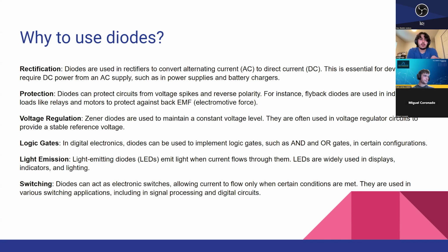Yeah, so diodes are basically like a brake, right? You want to prevent something from happening in your circuit. They work one way, but not the other way. One of the best examples of where a diode works is when you have an inductive load.